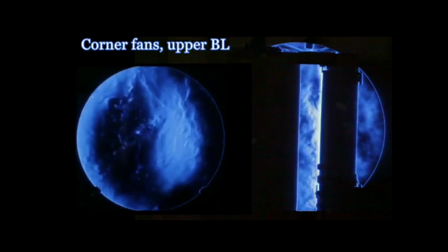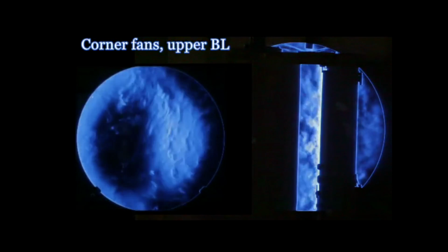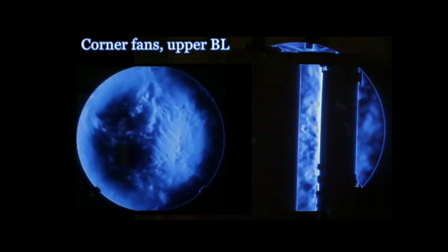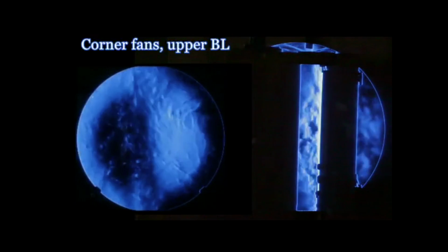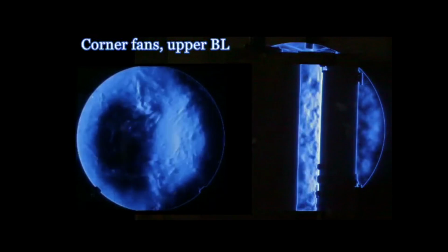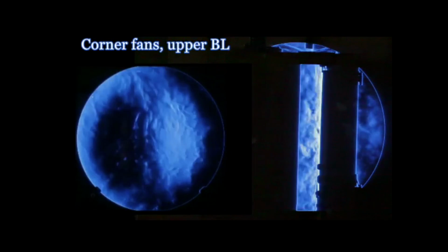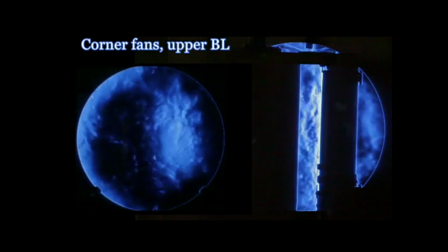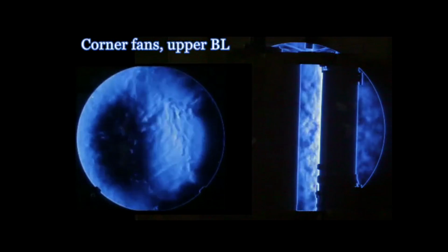But you still have an overall change of shape that's pretty much unavoidable, and it generally makes the mirror, I'll talk about this right at the end. So you can't compensate. It basically becomes a weather detector, the mirror does, depending on how much the temperature is changing. But my point was the desert is the worst environment to get a mirror cooled off in because the delta is the biggest. Midwest is pretty bad too. We have temps to go from 90 down to maybe 70, 90 plus in the summer. So everything's different. An optic is only measurable in the shop, is my point with all of this, for the most part.